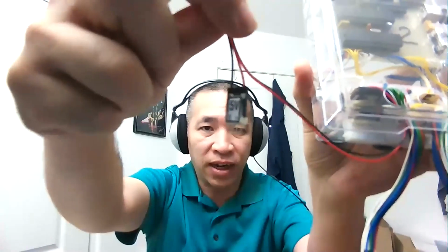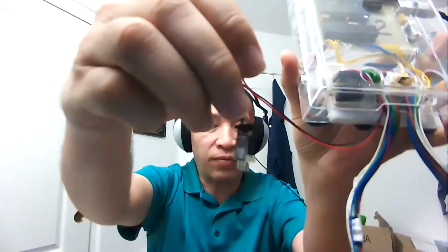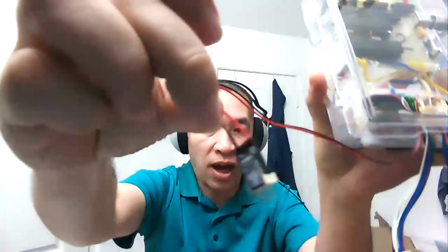It's a 4-pin connector. The red is 5 volts, and the black one is common. This is hooked up to your board. This is the board that I built for D-Lab 1, for example. D-Lab 1 uses port A and port C. So I have the control box, I look at my port A, this is my port A, and I connect into my port A.